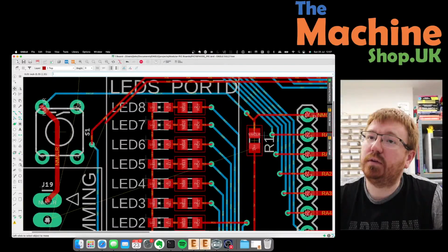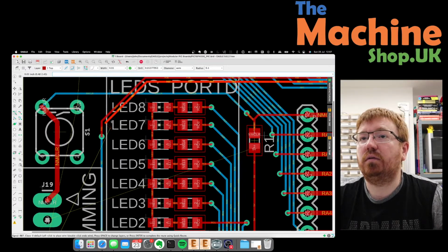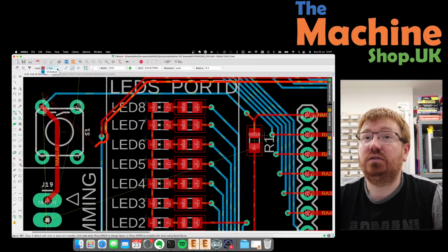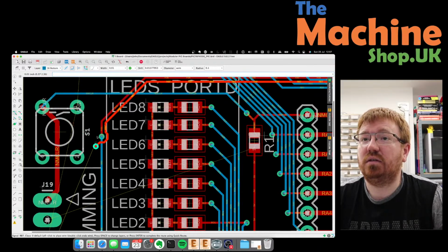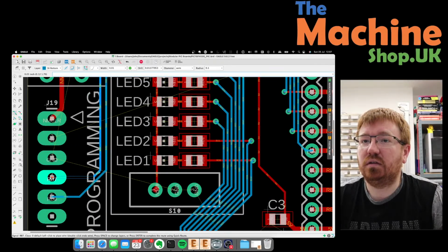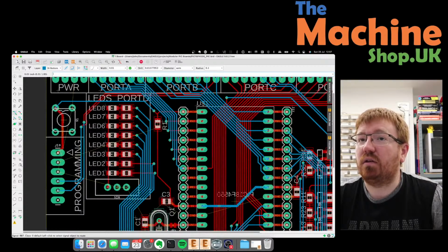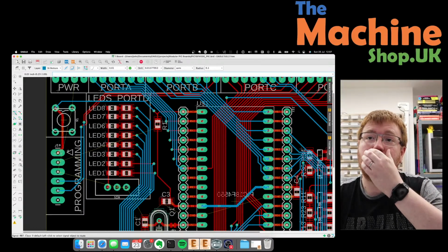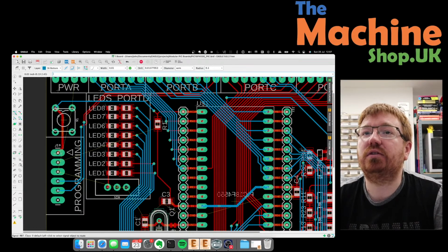Come on, Mr. Via. There we go. I put Via there. Put that there. And I can go from here. Haha, gross. To there. Change that to there. Cool. And then that blue can come nice on here to there. Which means I've now got all of this area in red to be able to route potentially power and 5V, etc, etc.